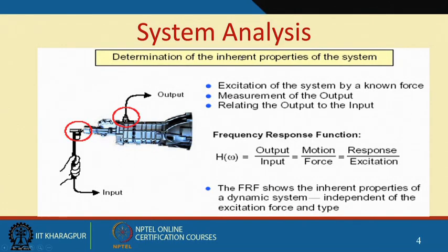And for the sake of completion, I will just mention modal testing being done through what is known as system analysis. It is this output by input, response by excitation. So, the frequency response function shows the inherent properties of a dynamic system, which is independent of the excitation force and type.